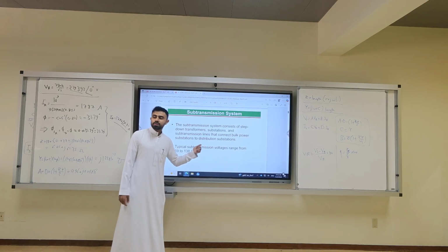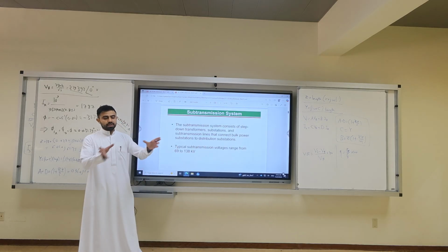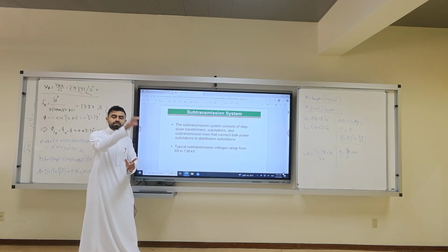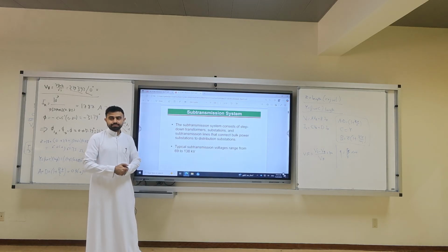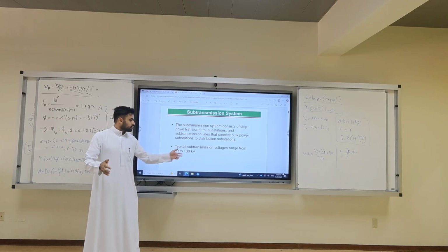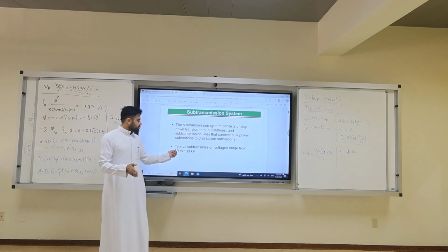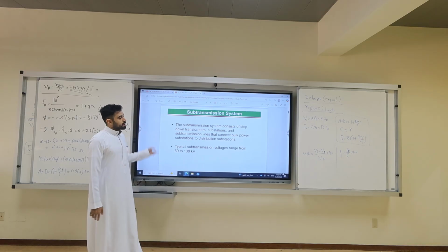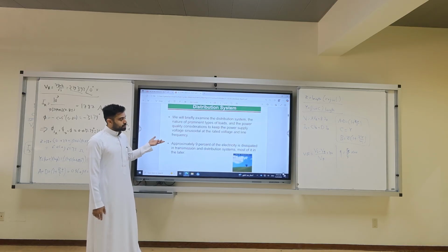So what is the purpose of sub-transmission? It's the bridge between transmission and distribution, especially if the transmission voltage is too high. It may be 500 kV, reduce it to 138 or 69, then reduce it to distribution, rather than dropping it at one time. Next lecture we will talk about distribution.